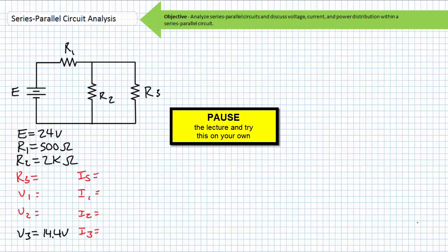We're being asked to solve for source current through each element, the voltage drops across R1 and R2, and the value of the unknown resistor R3. Use basic series and basic parallel circuit properties only. Since this circuit incorporates unknown resistors, you cannot rely on the reduce and return technique. Don't even attempt to reduce it to a single total resistance because you can't.